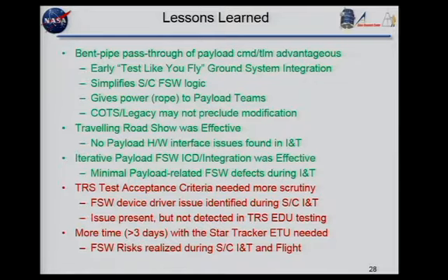When we worked with Lockheed Martin, their software for interfacing over the RS-422 reused the IP protocol. So we had to add an IP protocol to our software around the interfaces, on both sides. The lesson learned was you can push back on these payloads, and if it makes sense, they can pull a CCSDS wrapper off their data or put one on just as easily as you can in your flight software. It would also allow you to get this bent pipe working earlier.